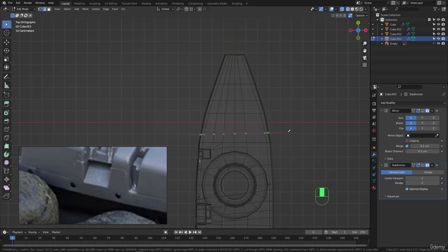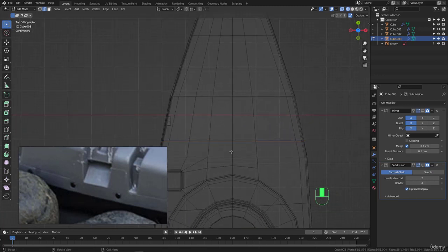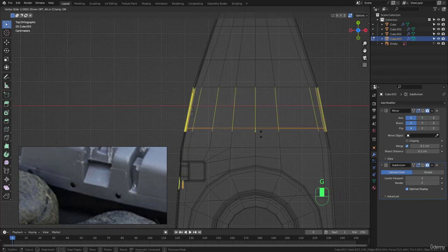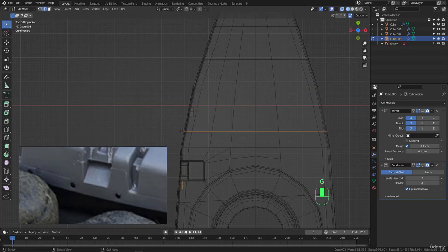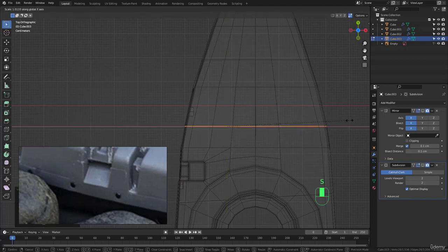If you want to make the cut straight, just hit A, and that's it. And then hit C to cut through the whole geometry. Confirm the cut and then hit enter. Alright, after that you can hit G twice and slide the, sorry, let's grab this one alone, G twice, and slide this just a little bit right here. And scale it just a tiny bit, not too much.